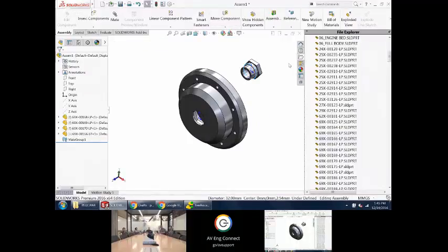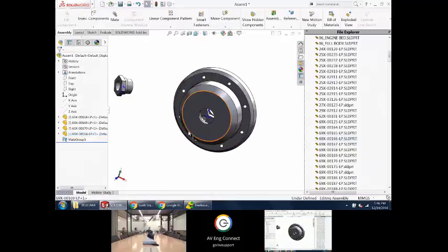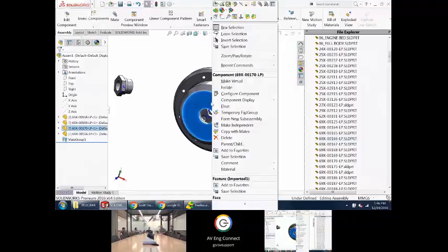When you click and drag on a component in an assembly with the left mouse button pressed in, you're moving axially. You're moving along one of these X, Y, or Z's in a line. If you right-click and drag, you can rotate about the X, Y, or Z. So that's a little bit about motion, getting these things placed in place. The left is a linear, right is a rotational.